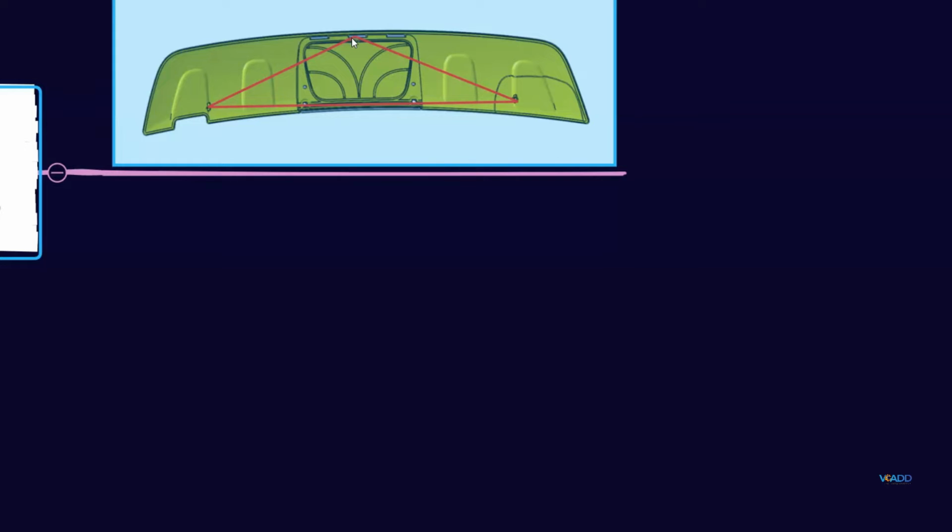Again guys, this position of attachment depends on your counterpart. I'm telling you that you should have an attachment here, but parallelly you should check whether you have something there, means this part is attaching somewhere, right? Suppose you have created a snap here, but that snap is going to attach in some slot, right? And that slot should be there in your counterpart. Again, that thing also you have to think.